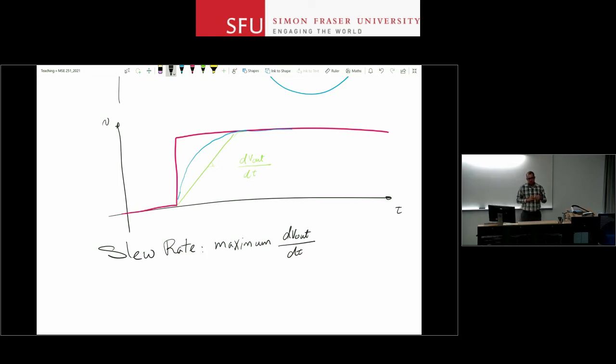And if your input signal is too large for these guys to handle, you actually push those devices, or some of them, out of their linear range. So all of a sudden, you had these transistors that were all biased in their active region, and you may turn one of them off. The current that was used for the biasing of that transistor is going to go and charge up a capacitor. A current source biasing a capacitor gives you a constant voltage going up or down. And that's why this happens.